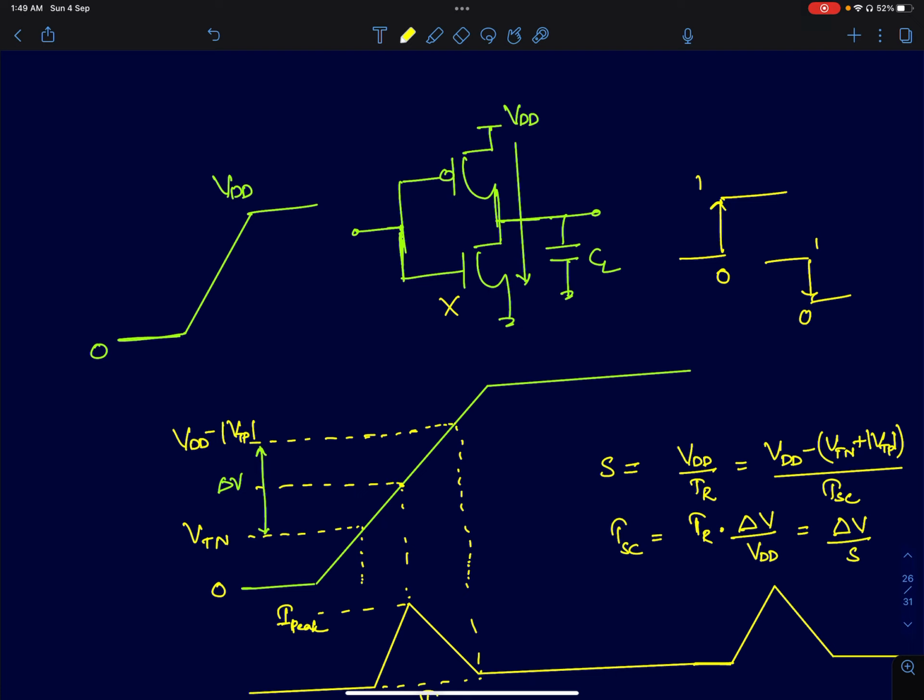And immediately the PMOS will then start charging the capacitor. But in reality, most clock signals will have a finite rise time. Because the rise time is finite, you will not have this sudden mode of operation where you have one device turning off and the other device turning on. Instead, you will have a gradual shift, a gradual handoff between one device's conduction to the other device's conduction.